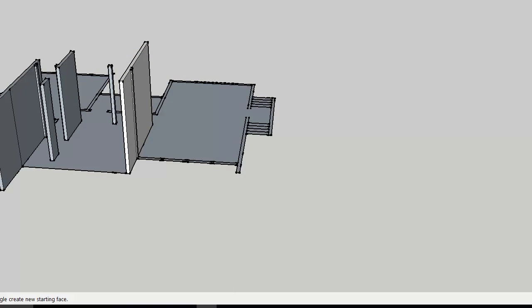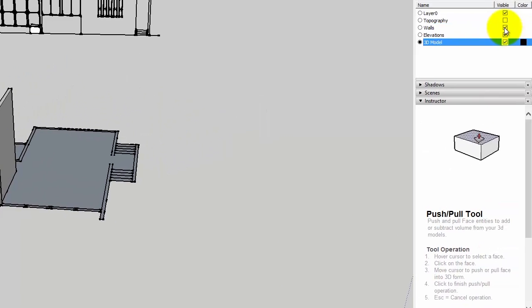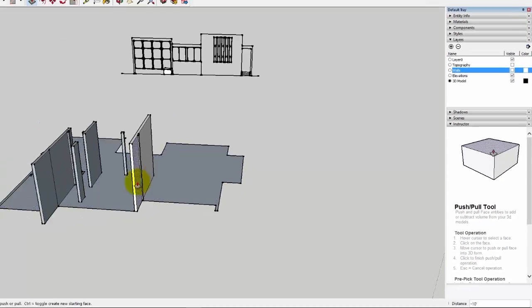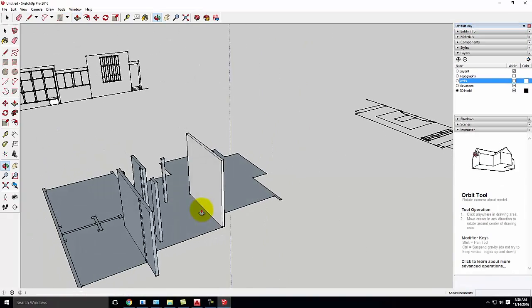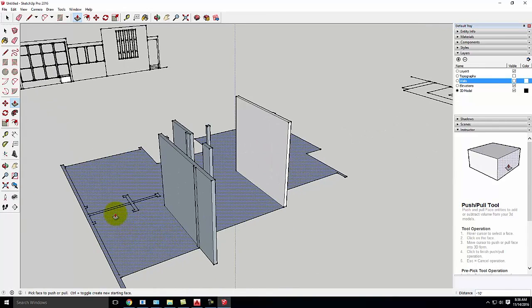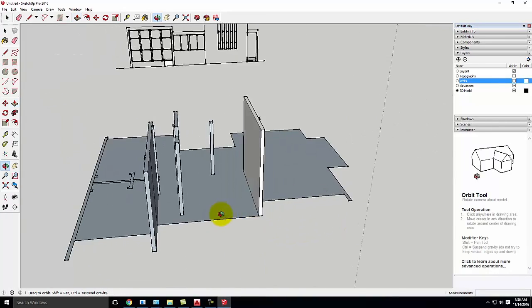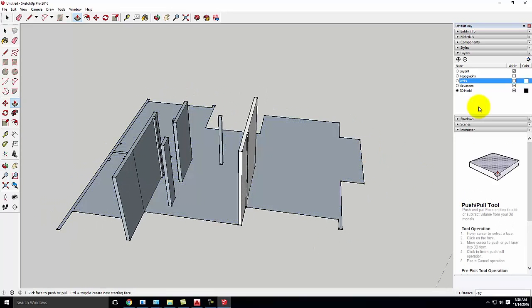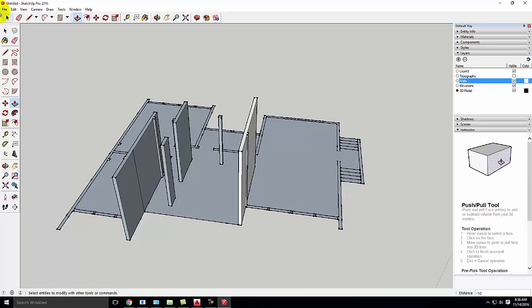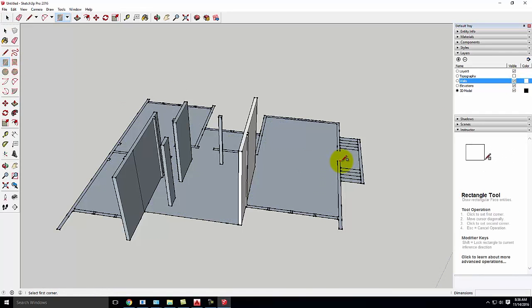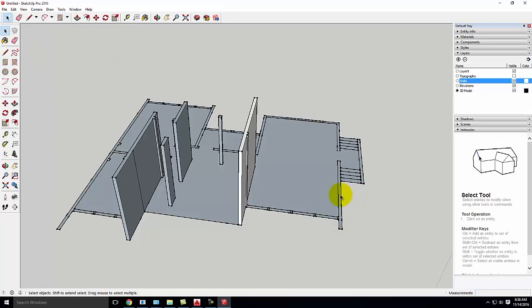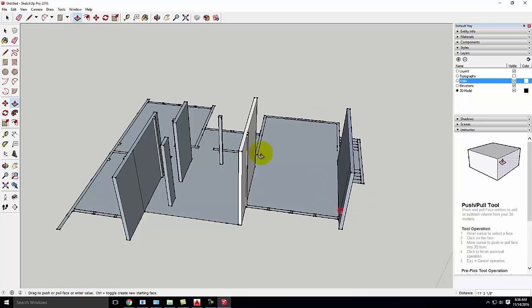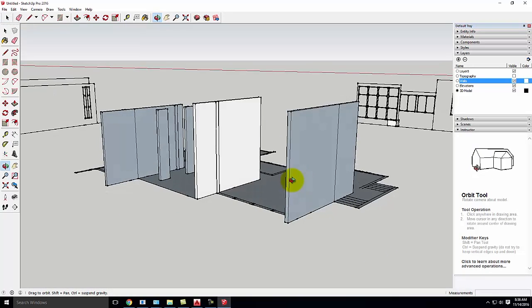Remember, because we're drawing on the 3D model layer, I can choose to turn off the walls, and you can see what the floor plate looks like without my little divisions. Okay? So we could go through and continue. I could draw more walls, and we could continue extruding. At a certain point, let me turn back on the walls here. Let me go ahead and draw this in. So there's that. Let me use push-pull, and I'll make it the same height as that wall. So there we are with those two walls.